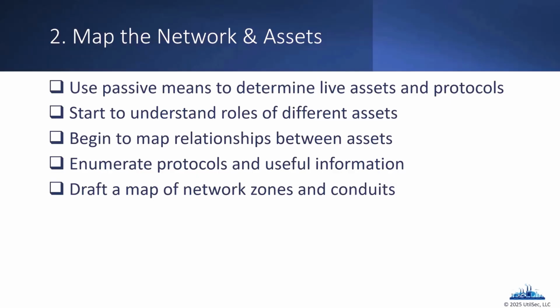We can start looking at, well, what protocols do we see in the environment, right? Because different protocols operate different ways, especially in the OT world. And there's certain pieces of information we can get from protocols like Modbus, and it has some differences with other OT protocols like S7 or DNP3, or maybe like BACnet. So we want to see what's in the environment, how they're talking, right? Read the information, look inside those packets to see what useful information we can use for mapping out the network and determining what relationships we have between assets.